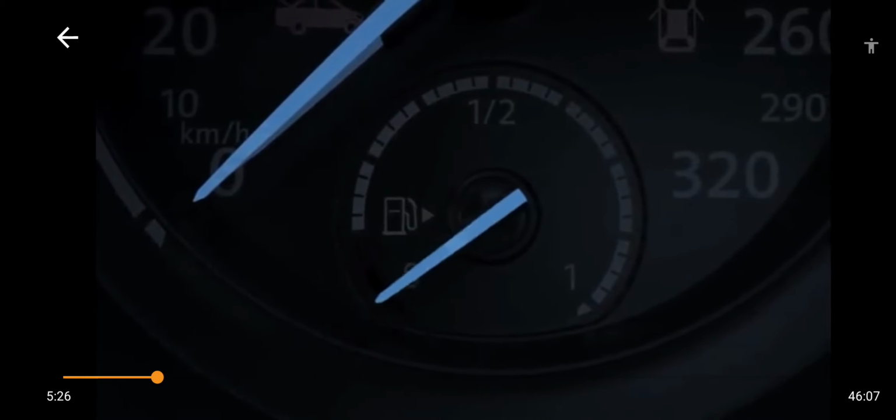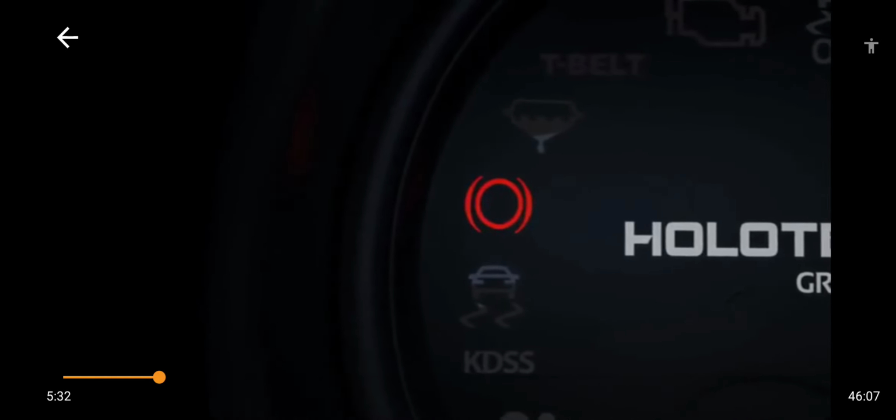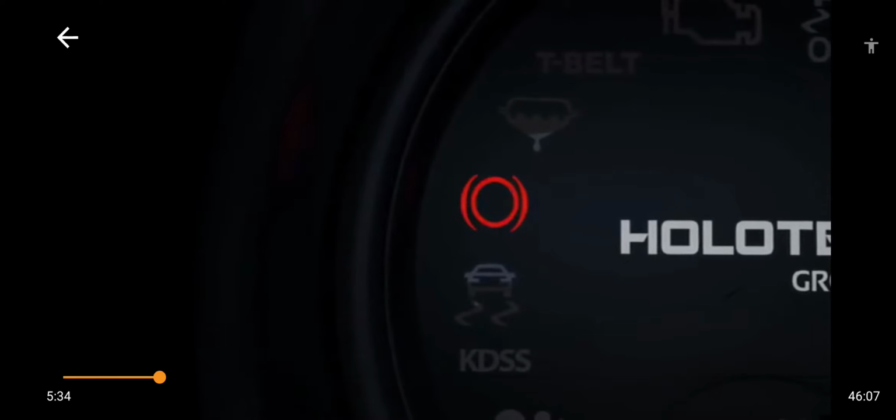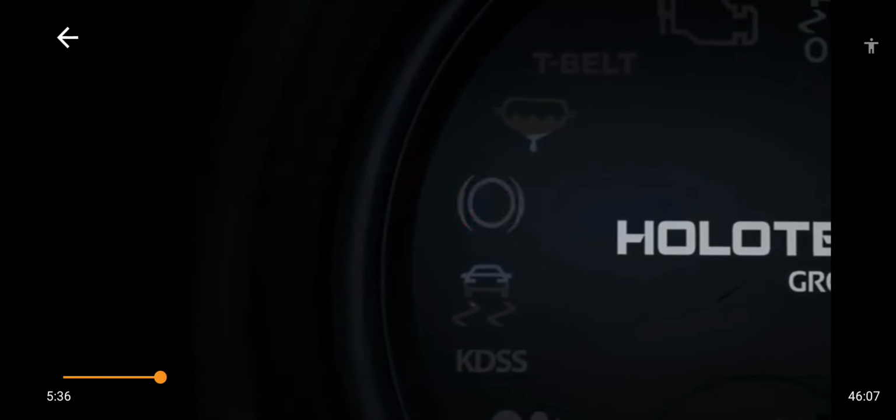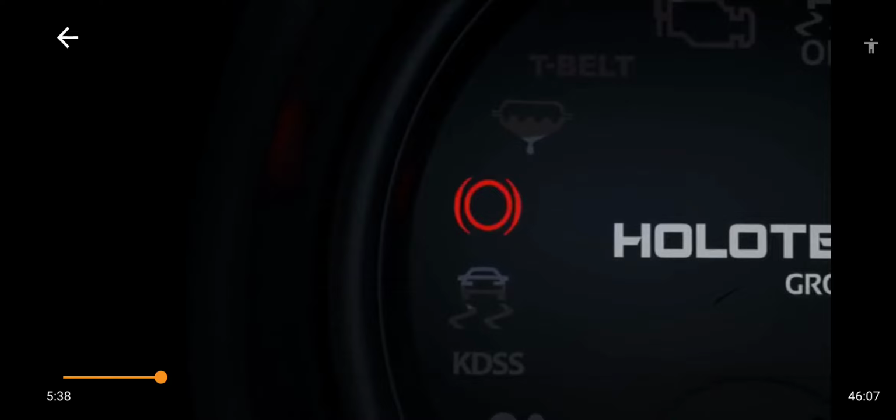Brake oil level or brake fault warning indicator. It should be turned off after the engine is turned on. Otherwise, check the brake oil. Handbrake warning indicator. The handbrake should be released before moving. Vehicle doors close indicator. Vehicle doors should be closed properly.